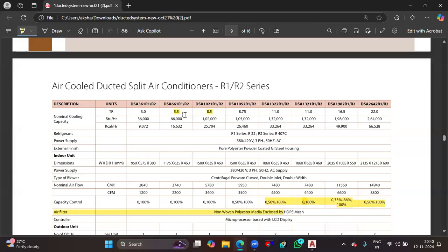If you're working for Daikin, the Daikins will be having certain ductable lineups. So just go on and take those values. Once you finalize this machine, then the next thing that you need to check is the nominal airflow. Here, they provided the value both in CFM and CMH.